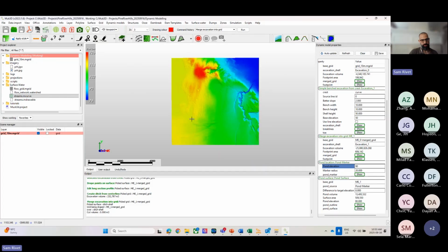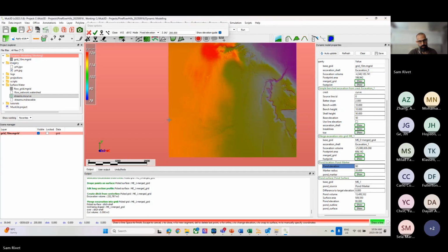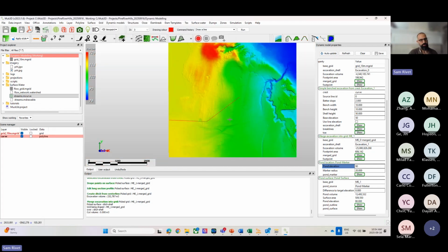Okay, so I'm going to draw a center line here. It's going to float it above the ground by 5 meters. So once again, same process, polyline, draw a line, put it at 200. Semi-road starting here. It's coming like this. I'm going high to low. Let's say I just run it till there. Pretty simple configuration.